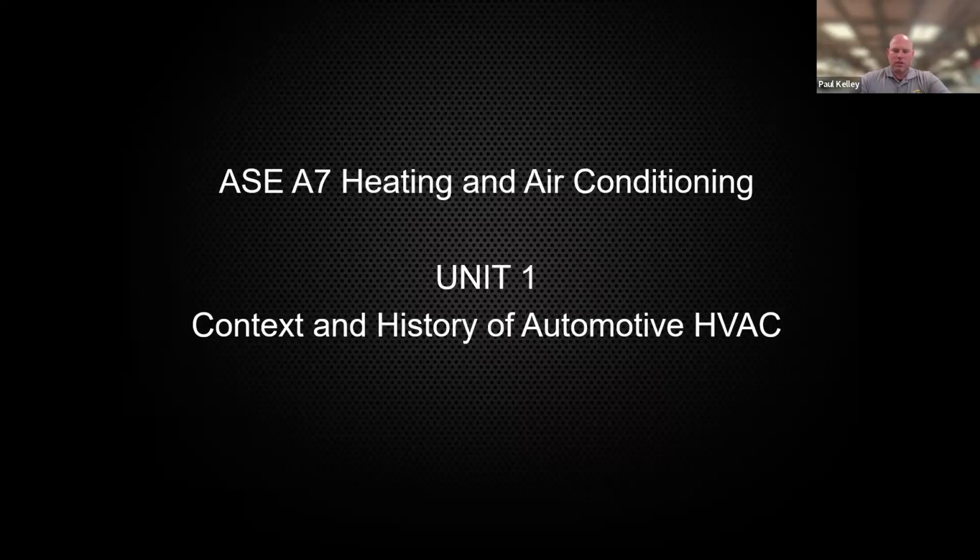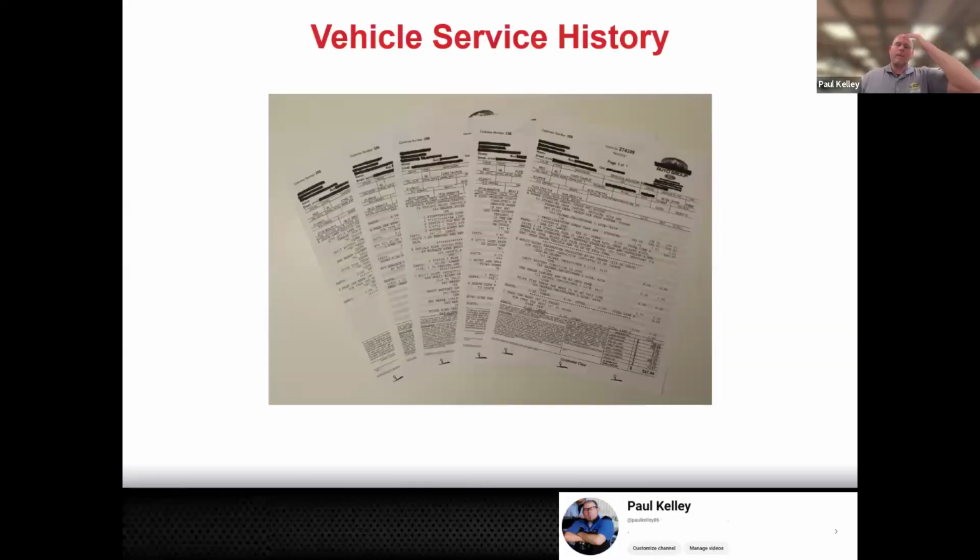When we get into diagnosing the vehicle, we need to know about the service history. The reason this is important, some jobs that we have to do will require us to recover the refrigerant out of the system. So let's just say a car comes in and their concern is the AC blows warm, which is the most common concern in AC. If you were to see that they had recently had the engine replaced, when you go to replace an engine, you have to pull the AC compressor off. Typically, to pull the AC compressor off, you have to recover the system. After you're done putting the engine in, you're supposed to recharge the system, do the full AC service.